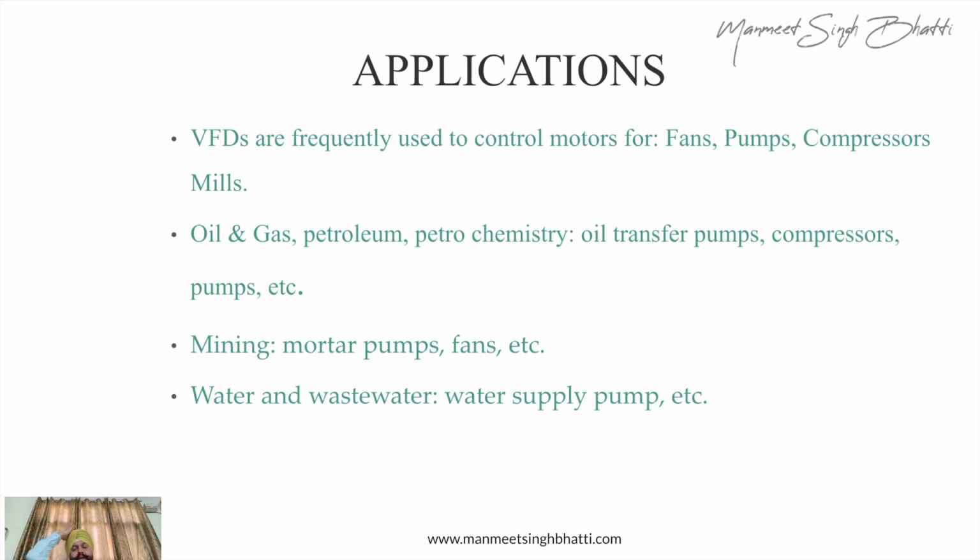But the catch over here is, if that VFD is going to control something, like a voltage, a load, or a frequency, only then you should go for a VFD. It is not required to put in a VFD if you are not controlling anything. It's always better that you control it. You may reduce the speed by maybe 5%. That 5% is actually going to get you some kind of saving. So that is the reason for putting in a VFD.